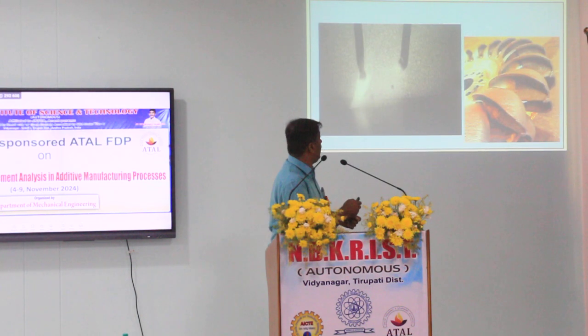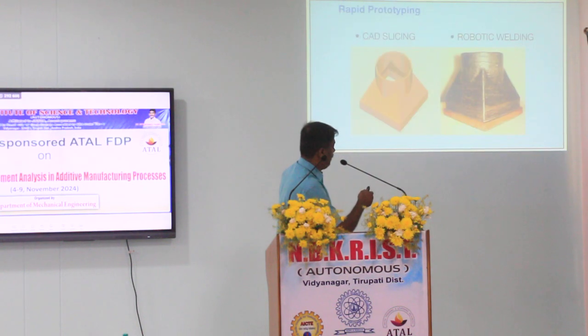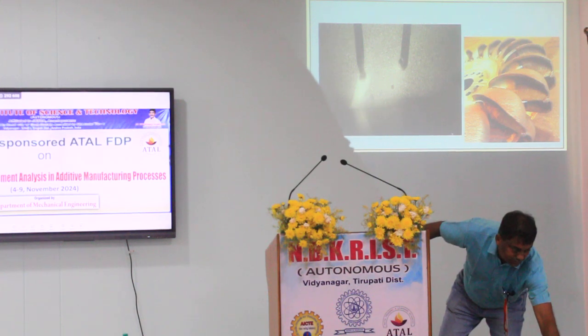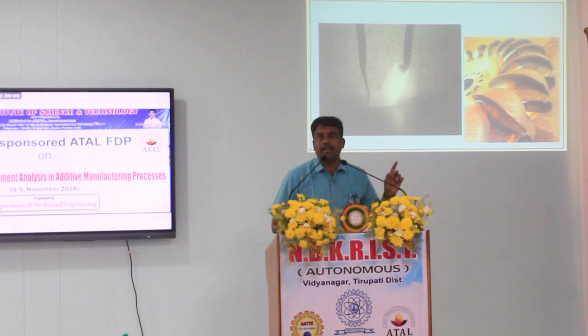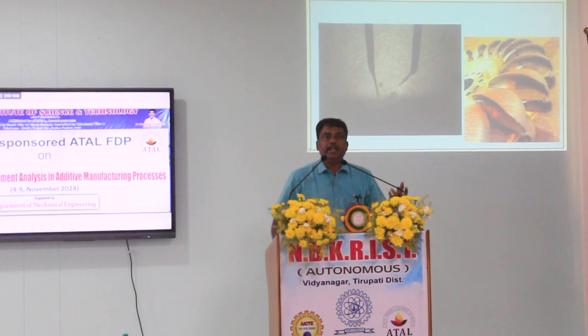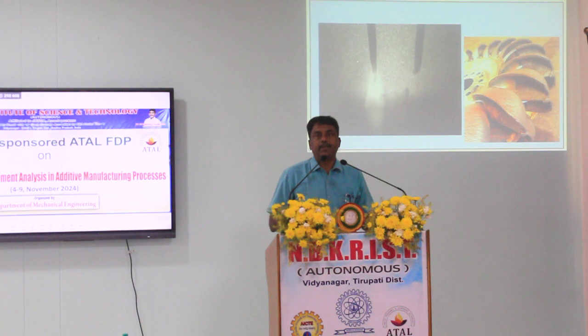Right? So what you see here is one such process, where we use a tandem MIG source. This is a high-speed video. So what we see when the tandem MIG process is in operation: you see 2 electrodes are simultaneously fed and we form an arc, and these 2 wires can also be different material, or the same material.